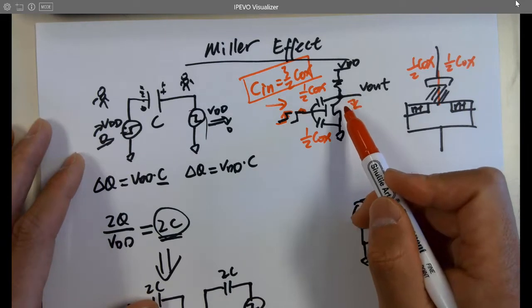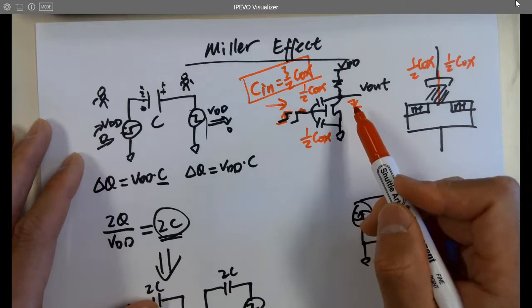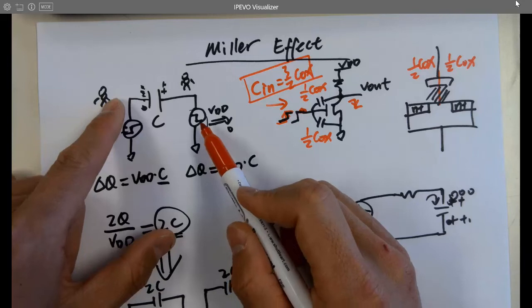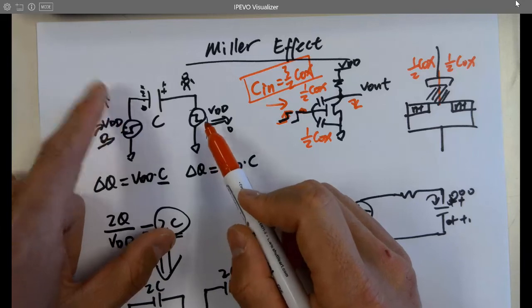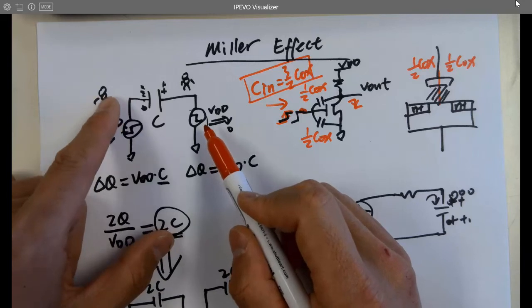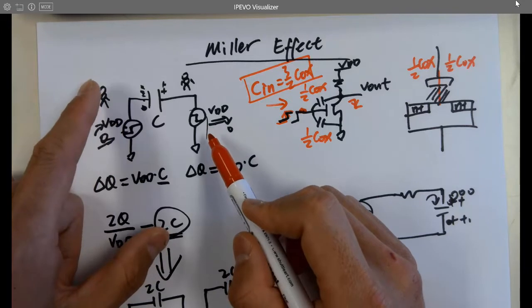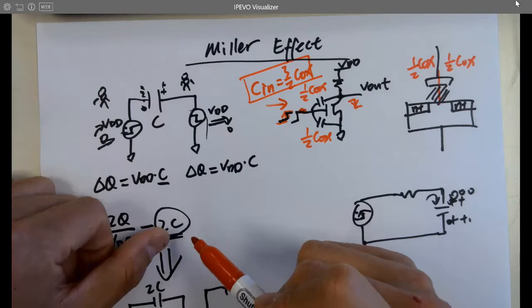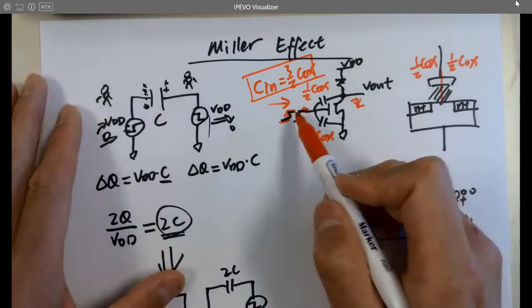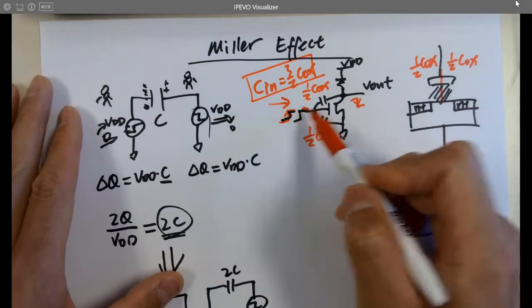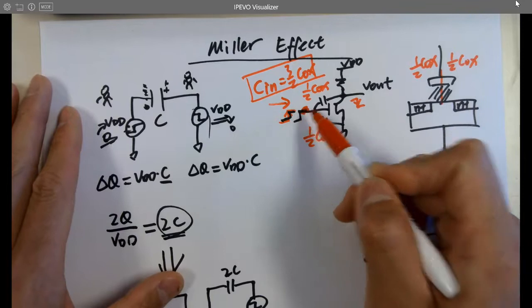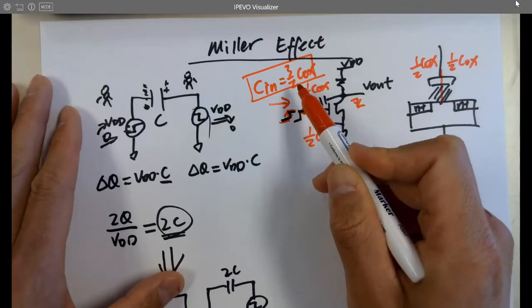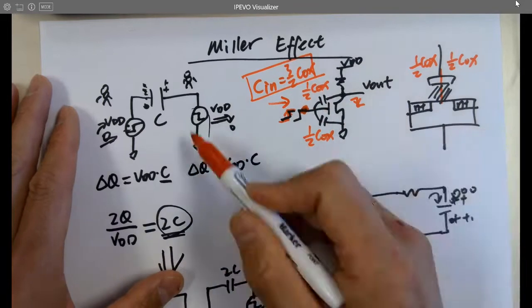The Miller effect only takes place when both sides are being charged. Yes, because it charges and discharges. Charge and discharge, two sources happening in the opposite way, right? So it's doubling that effect. If one side is tied to ground, it's not receiving charge. It's important to know that, because whenever you are calculating the time delay from this point, you have to know what the effective capacitance is. That's why we need to model it that way.